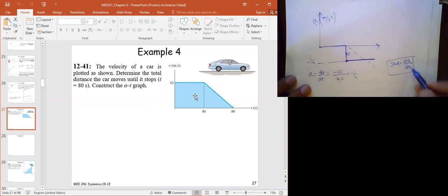You don't see that in what we're doing, but for a machine to have very smooth operation, the jerk would have to be continuous. What would the jerk be here? It would be infinite, because over a dt you are jumping from here to here, so the slope is infinite.